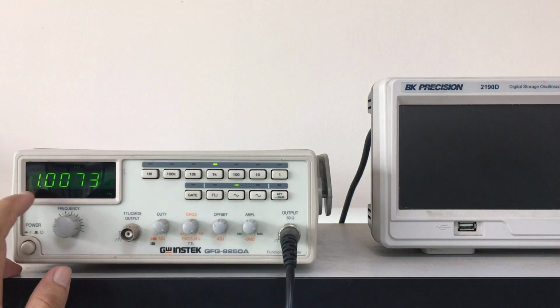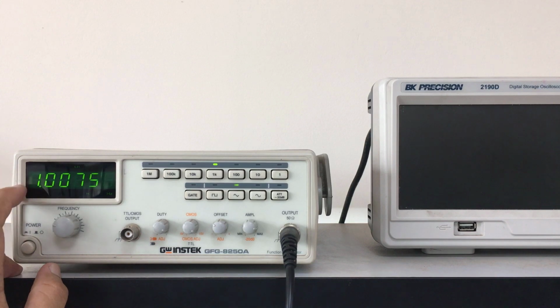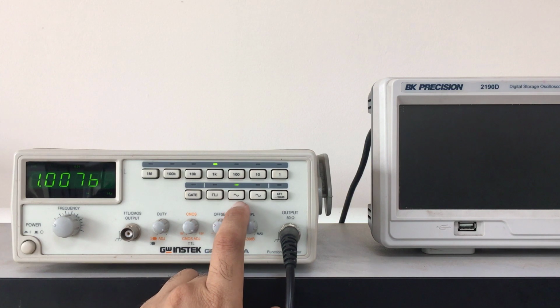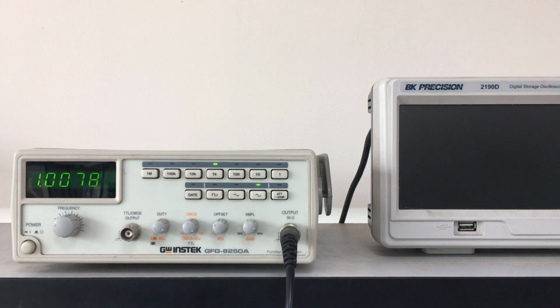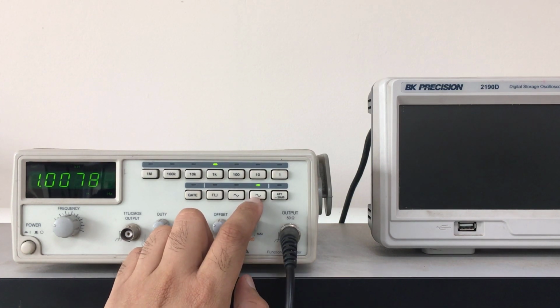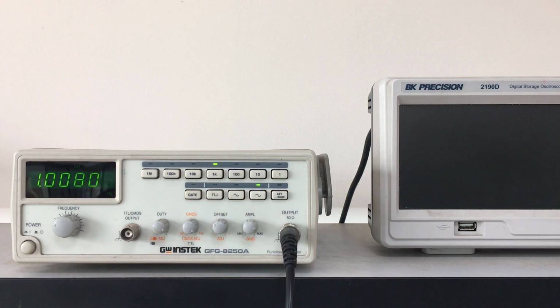and we see that by default 1 kilohertz frequency is produced as output, so we don't need to adjust it, as we need 1 kilohertz. And as always, the default signal generated is triangular wave. We produce sinusoid by pressing this sinusoidal button. So by pressing the sinusoidal button, we create sinusoidal output. So to adjust the amplitude, we will need to move on to the oscilloscope.